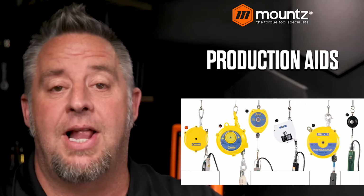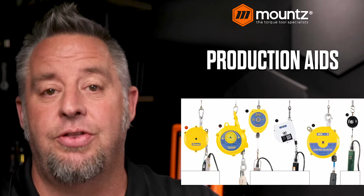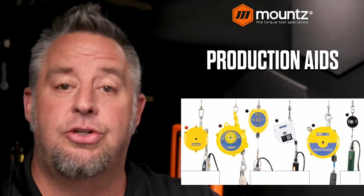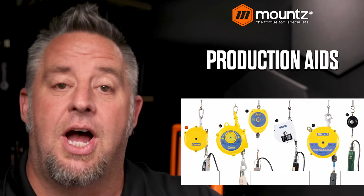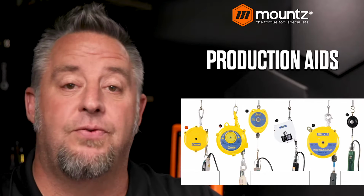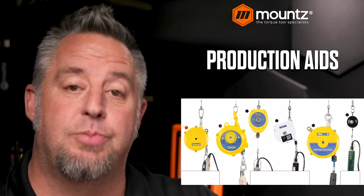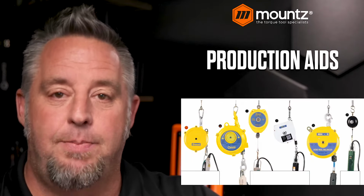The zero gravity balancer works a little bit differently in the fact that there is no tension placed on the tool itself, but it allows the operator to move the tool up and down the stroke availability, and the tool will simply stay at that location until it's moved. So the zero gravity balancer has no tension on it, but it does allow for the free movement of the tool, with no additional tension that may be created by a spring tension balancer that you may see with that type of production aid.